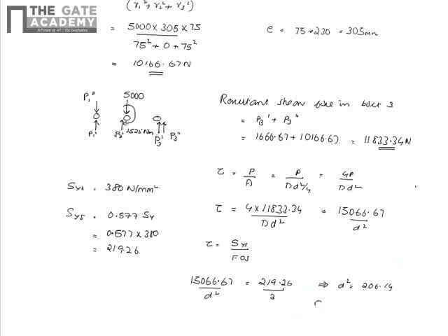And d will be almost equal to 15 mm. So in this case, in the worst case we can go for more than M15, like M18 or M20 bolts can be used for this application.